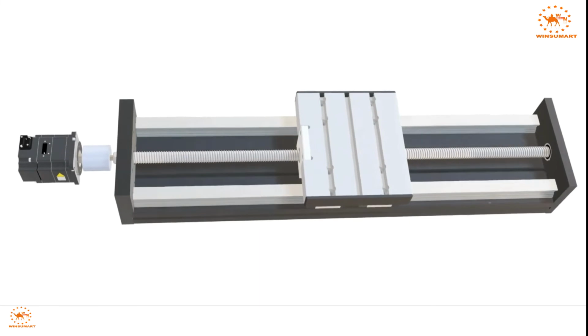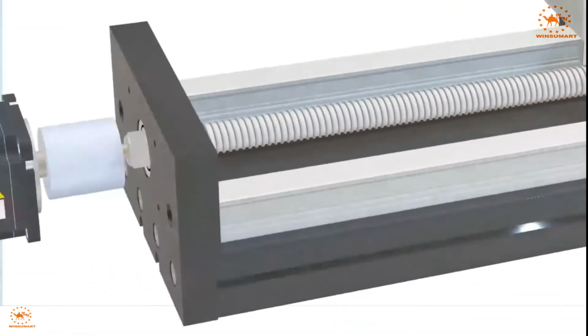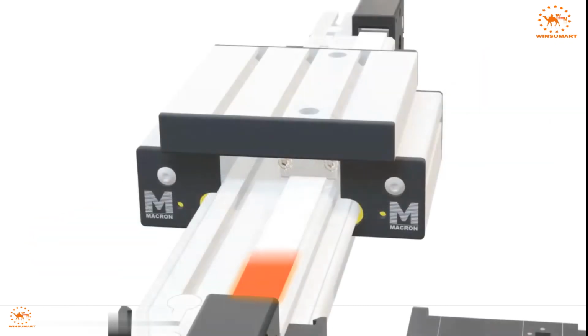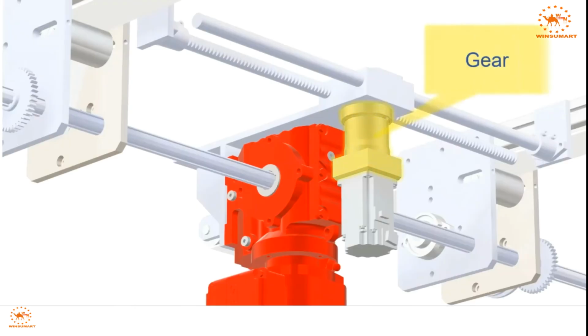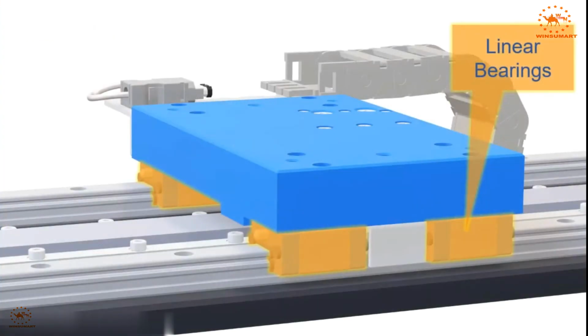But these mechanisms have other moving parts that wear out. The screw itself, the nut, the bearings on the screw, motor bearings, belts, rack and pinion, and gearboxes all wear out even with regular lubrication. From day one, the performance of these mechanical systems begins to decline. The backlash and stiffness get a little worse every day. Therefore, expect positioning time, accuracy, and repeatability to continually degrade as time goes on. The linear motor bearings do eventually wear out, but quite gracefully by comparison.